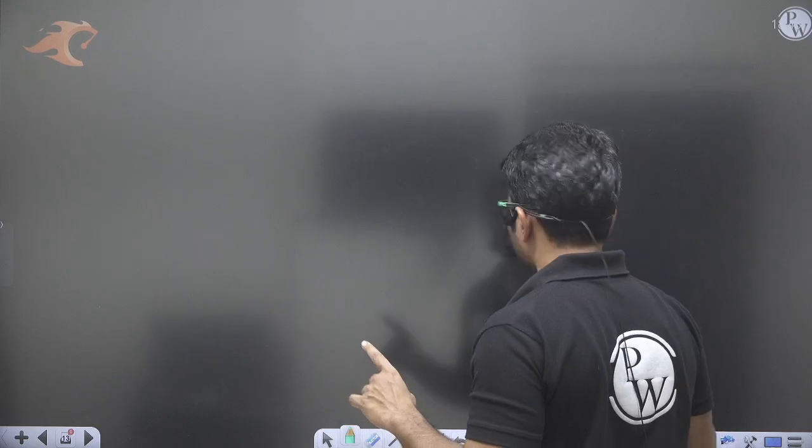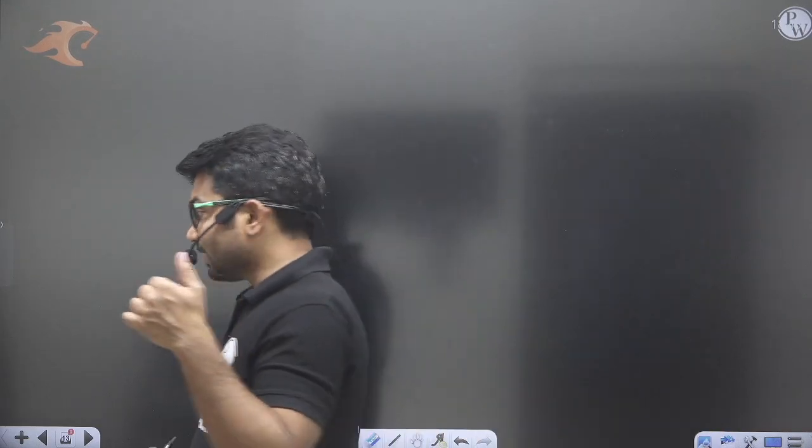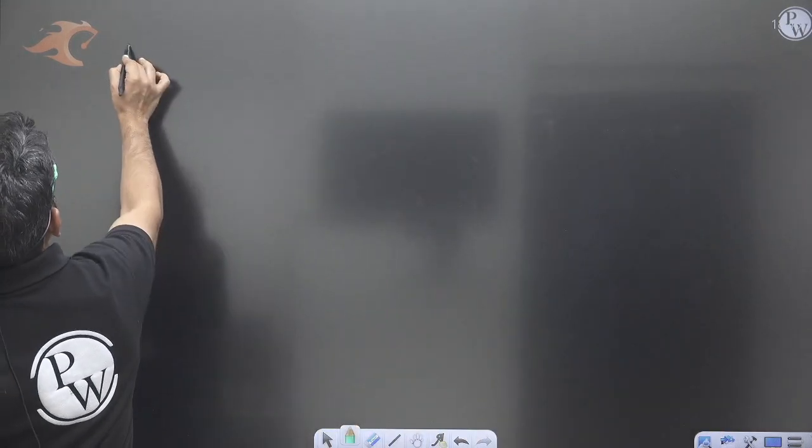With each repeated loading, the width of that crack will increase, and suddenly it will become so large that the remaining material will not be able to resist the applied load. So fatigue happens due to progressive cracking of the material.